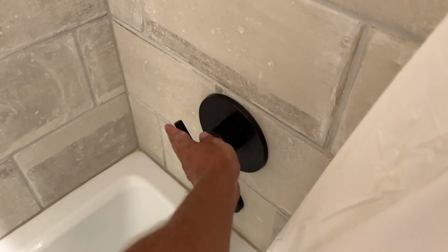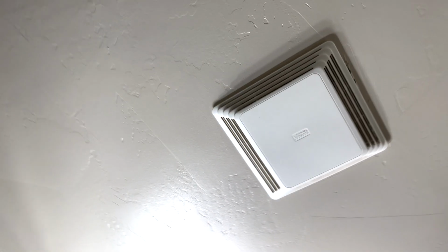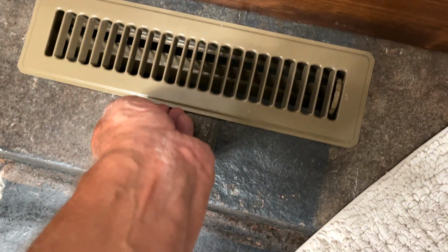I use the side of my leg. And then hot and cold water at the tub. Make sure it drains and the walls look good and secure and sealed. Nothing loose at the pipes. And the bath fan exhausts. We saw the hoods on the outside. The door opens and closes and the floor looks good. And sometimes I like to open a floor vent just to see. Not that one. And that's loose. Towel rack.